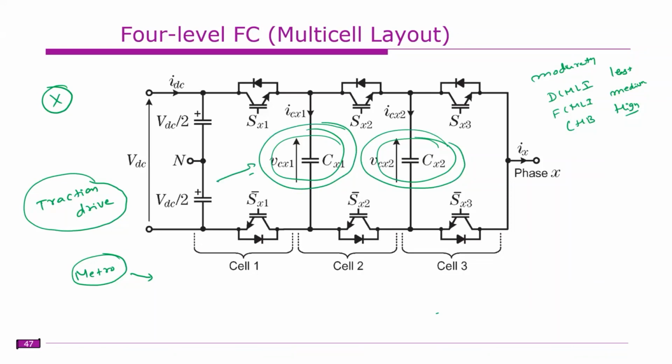During this regeneration process, most trains nowadays, in the early days, used DC series motors, right? Because of high initial torque. Now with the invention of direct torque control, the starting torque can be increased by using advanced torque control schemes. So now we are using induction motor drives. This induction motor drive is usually fed by a two-level inverter or some multi-level inverter.